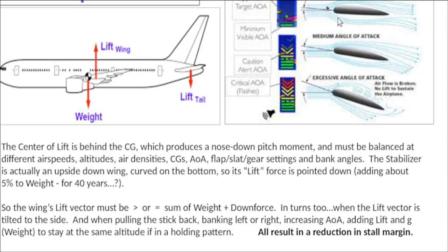I've included this so you can see what we're talking about with angle of attack. So in this wing up here, the relative wind, which is what these little vector lines and curves are, is hitting directly into the front of the wing and going smoothly over the wing. And this curve causes this air to move faster, and that makes it be a lower pressure on top of the wing, which creates lift. And also this section underneath deflects air downward, and that creates lift too.